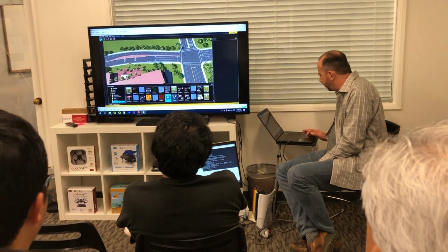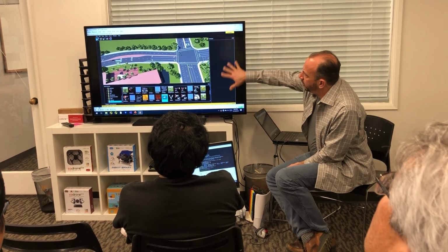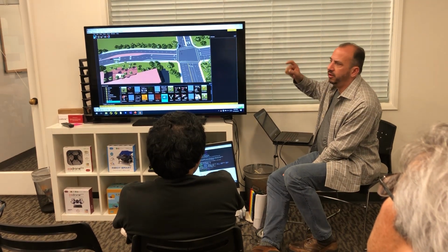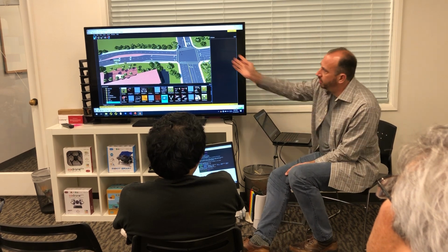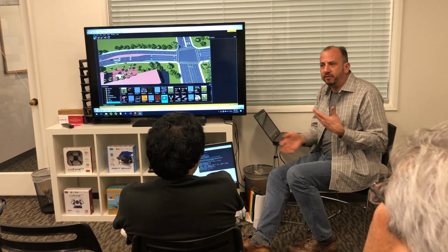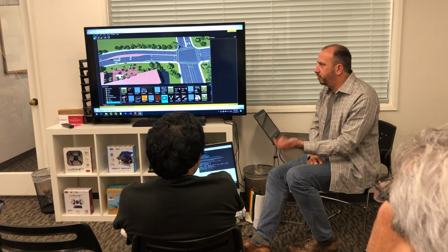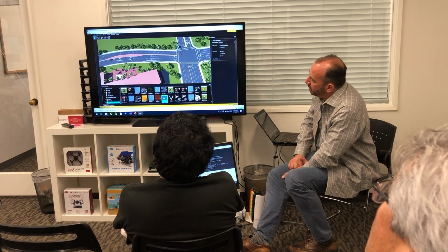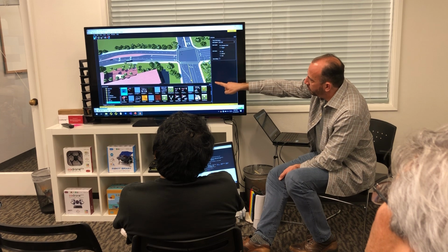So this is our scenario demo video. I'll kind of walk through it, but this is all in the same editor, so this runs within the same user interface. You can build a road network and then switch over to the scenario mode, and then it changes the toolbar at the top. You have a different set of tools. You can edit your scenario, and then you can actually go back and edit roads as well in the same tool. So this is placing the hypothetical test vehicle. It was supposed to start over there and end up over here.